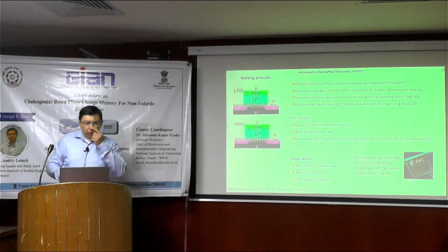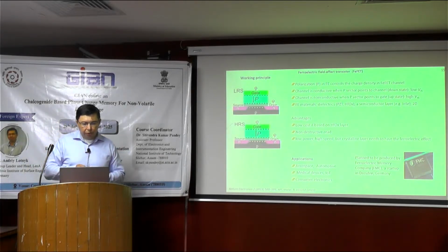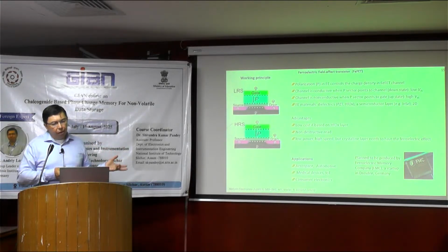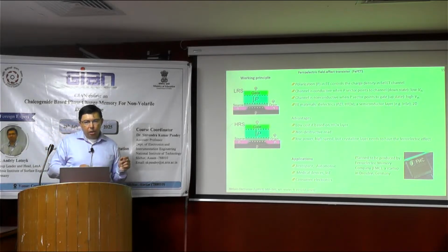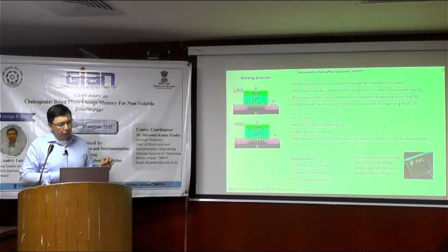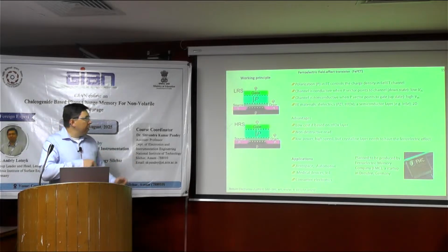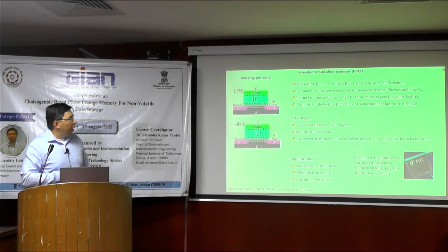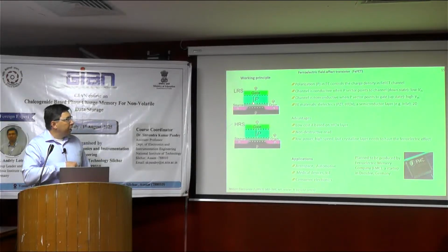So now let us consider the working principle of the ferroelectric field-effect transistor. It's similar to the transistor we considered above, but in this case, instead of using floating gates, we use a ferroelectric layer. Here you can see that polarization in this layer controls the charge density in the FeFET channel, and the channel is conductive.